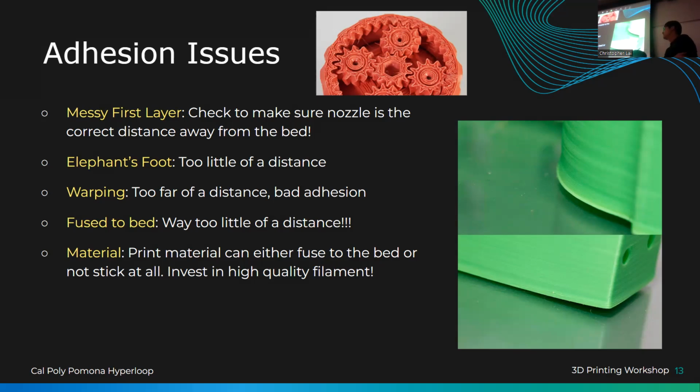The thing that makes them expire so quickly is that they're porous. So we calculate the porosity, that's a fun word, basically how much it absorbs atmospheric water and other junk. If you leave it out for too long without vacuum sealing it or baking it, whatever the case may be, you're going to have bad plastic. It's blobby, it's disgusting. It snaps and it doesn't quite fit right. And that little robot that you saw a couple things back, it's all bubbly.